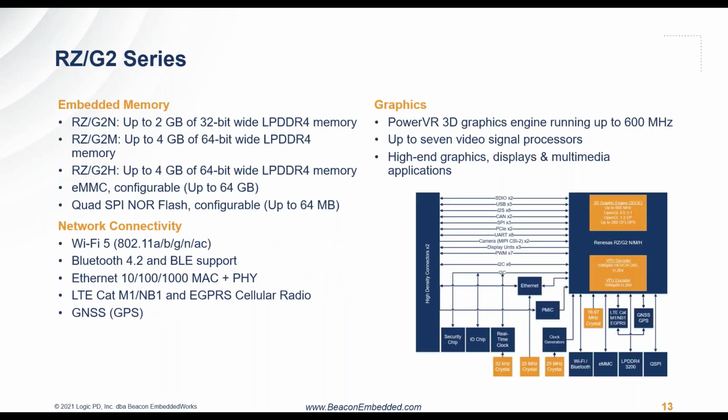It is a larger SOM. It does have other disadvantages like heat or size, but when it comes to the graphics performance, this is the best we can offer and one of the highest performing SOMs out there. It's also unique that in addition to the Wi-Fi 5 and Bluetooth 4.2 on board, we have an option for cellular on board as well, with an LTE Cat M1 or narrowband IoT cellular radio on board. So the graphics is the main seller, but the cellular options certainly help as well.